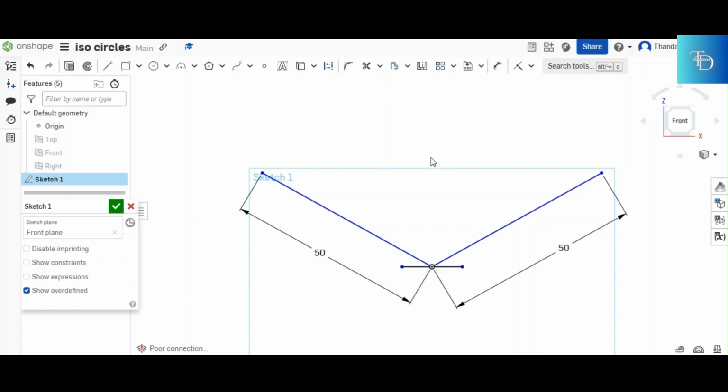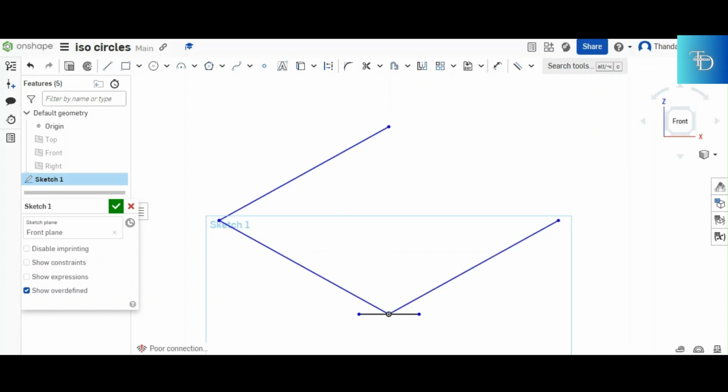You already came up with two sides of the square, so the side that is missing is another 50 millimeters that goes in that direction, and it should be parallel to that line. Every line that you draw, you use your 30-60 ruler and you use your 30-degree side to draw that line, and then you carry on and close your square. So now you have created your square.